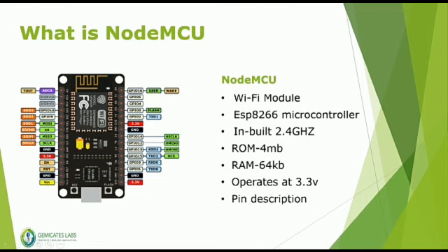It is used to transfer signals between two microcontrollers, RX and TX modules with asynchronous transmission. SD3, SD2 can function as asynchronous transmission or as GPIO pins. There are two reserved pins used by the microcontroller and cannot be used in connecting with any external circuits. NodeMCU has only one analog pin for analog communication. This pin is used for analog signal communication.